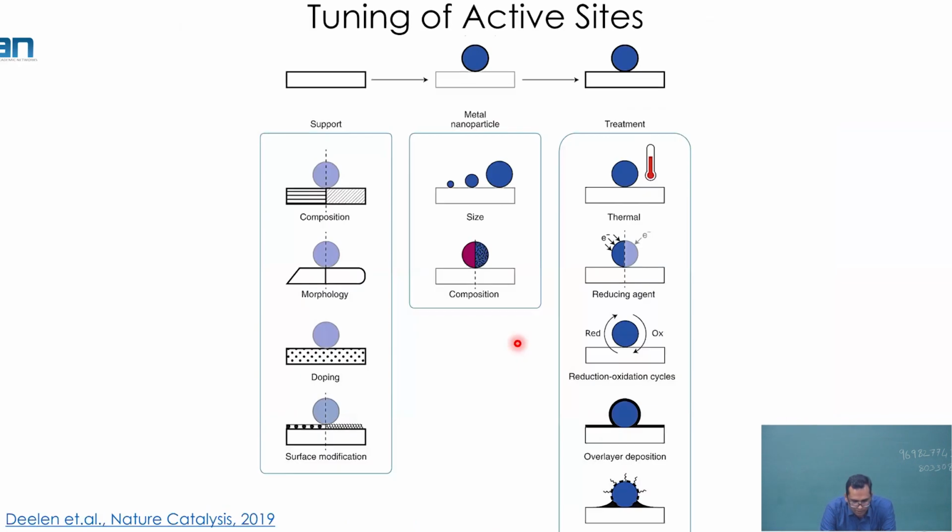Okay, and what is the effect of this migration? As you can see in the time on stream data, first of all, the catalyst activation under the reaction condition is taking a similar amount of time, but over a long period of operation, which is shown here over 40 hours, the catalyst which was treated in hydrogen for 50 minutes and the mixture of methanol, water and hydrogen for another 10 minutes shows a very suppressed deactivation over 40 hours.